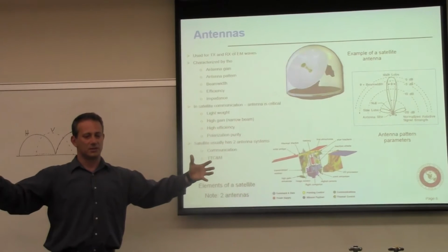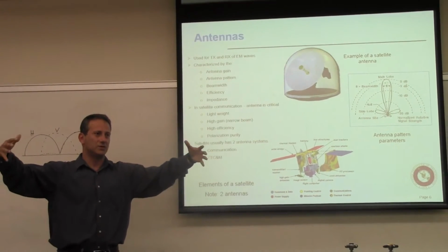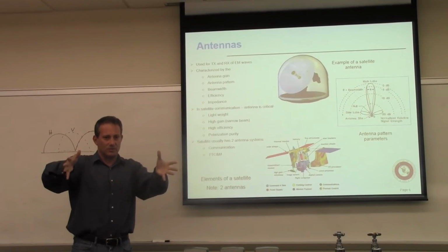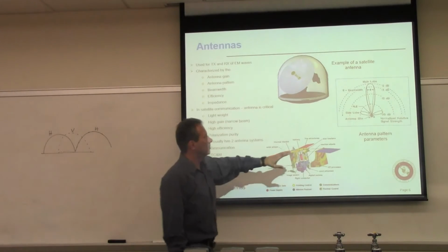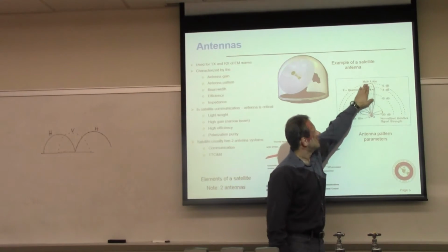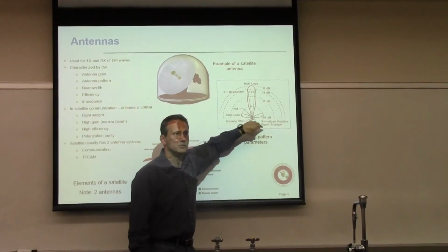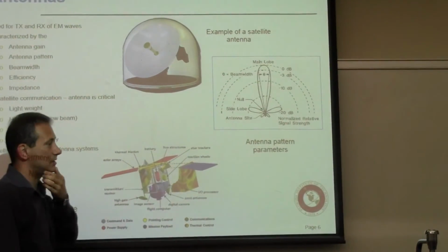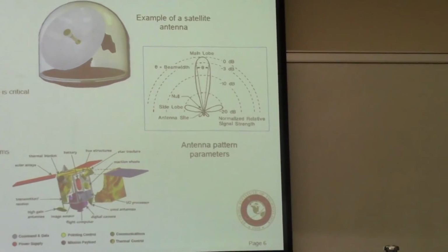You can think of it as a balloon. It takes all the energy that is delivered and squeezes it in a particular direction. That means that because more energy is radiating in this direction, it is at the expense of less energy being radiated in the other directions. And this is exactly what we want, because we want to radiate in one direction and spare all the other angles from radiation.